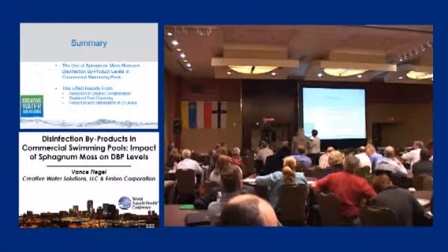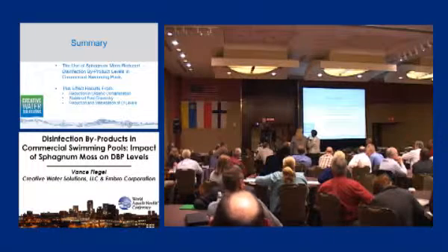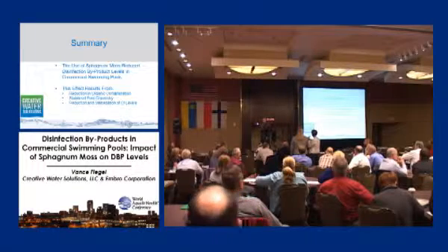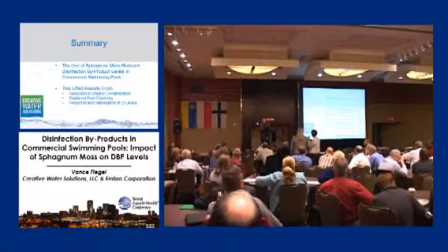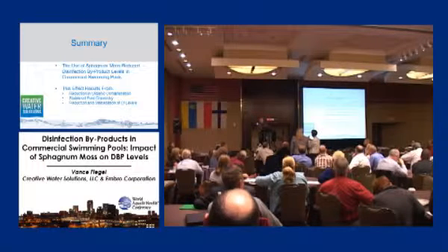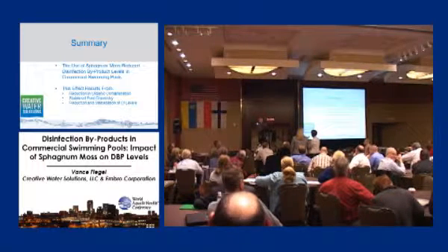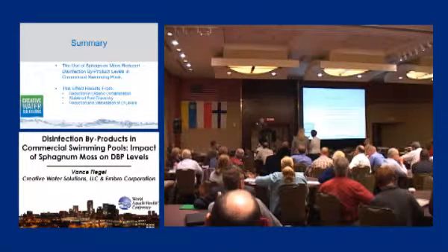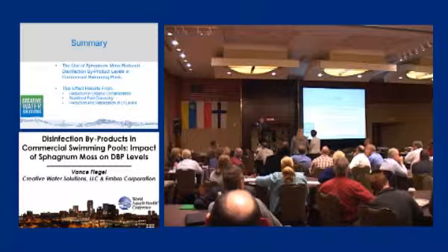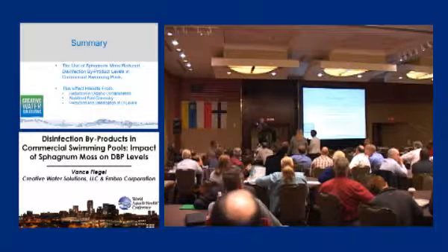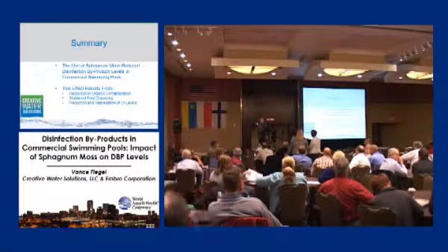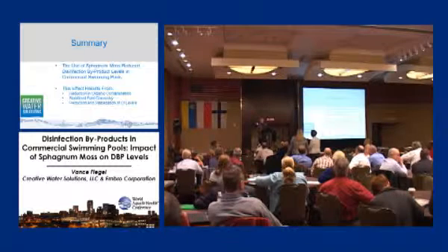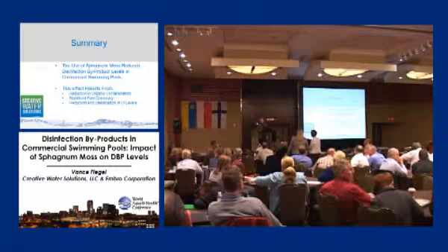My name is Stephanie Velagal. I'm a chemical engineer from Penn State. I had a similar question about the mechanism. I'd be really interested to know about that, but it sounds like you guys aren't so sure what the mechanism is. But then my follow-up question was, since it's an organic sphagnum moss, do you have any insight into why it doesn't impart an organic load to the water? It probably does to some degree, but we use gram quantities per 1,000 gallons. I think our standard dosage in a commercial swimming pool is 6 grams of sphagnum moss per 1,000 gallons of water. So it's probably pretty minimal compared to the rest of the organic load in the system.